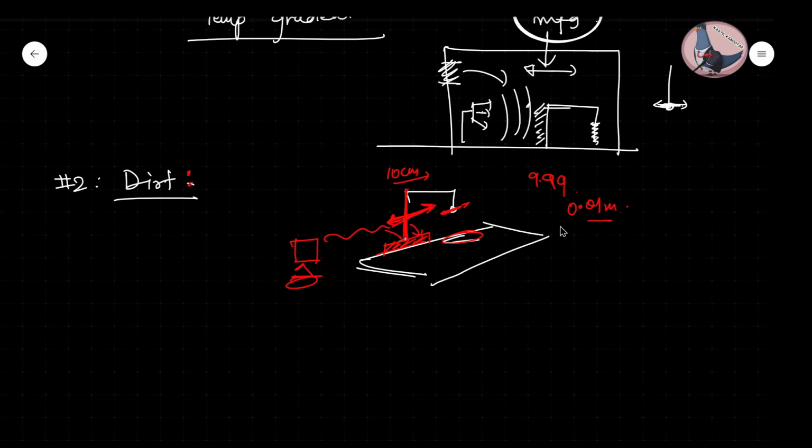So this point one, and then there will be some uncertainty in the measurement. So you can see this is the minimum error which will seep in. So these dirts will cause too much trouble. But suppose sometime you go to an industry, you will see this CMM placed just next to the manufacturing house, the place where the manufacturing is happening. Just next to it, the CMM is kept, and there you cannot control dirt so happily. So then you have to adjust with some amount of deviation which will come, and you have to do the trade-off between accuracy and portability.